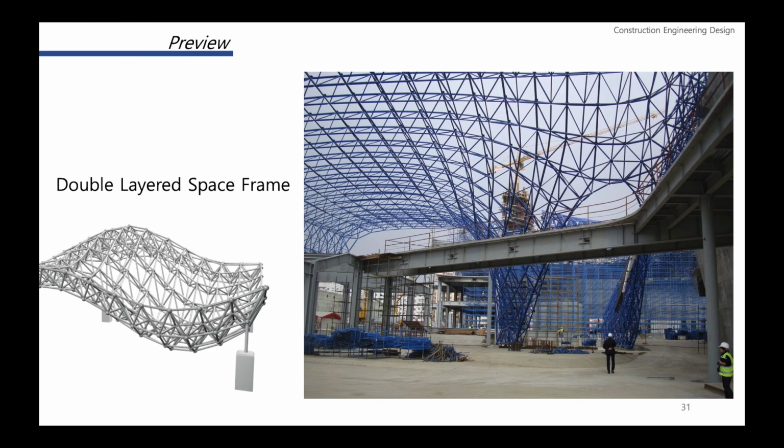In the Heydar Aliyev Center, double-layer grids are chosen for its formation. Double-layer grids consist of two planar networks of members forming the top and bottom layers, parallel to each other and interconnected by vertical and oblique angled web members. As the influence of bending or torsional moment is insignificant, it is commonly used for the realization of fluctuating facades.